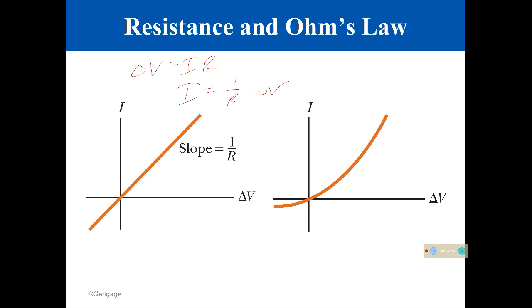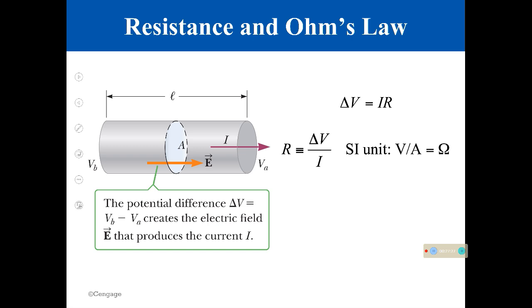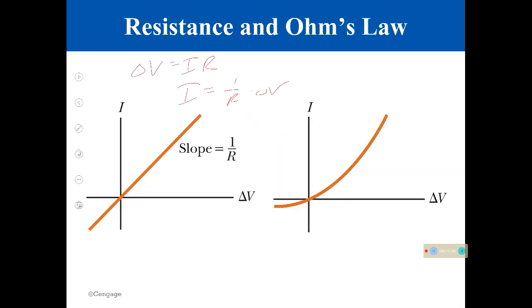Okay, so in this particular case, what are we doing? Well, if we get more voltage, we absolutely should get more current. And this just says if we get more voltage, the current is going to get even bigger faster, which perfectly makes sense. It's weird to see this, though. Actually, no, that's incorrect, what I just said, because it's the inverse. So actually, the slope here is going up. So what does that mean about resistance? Resistance is actually decreasing. This is not the typical thing that you would see happen in this case.